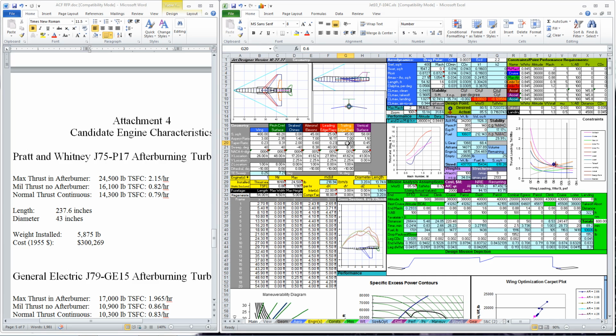Alright, let's go fix the vertical tail. Well, first off, the vertical tail can go further back, and that's going to help. And then the vertical tail can get bigger, and that solves the problem. Alright, and then our horizontal tail looks silly. It's very tiny. Let's go to maybe 100 on the horizontal tail for an area. And not only that, let's move it down.